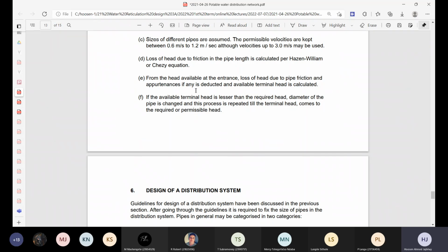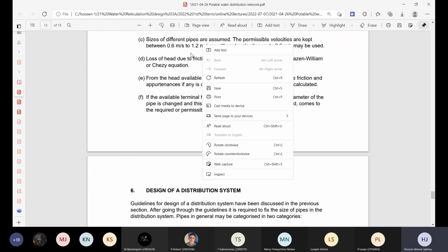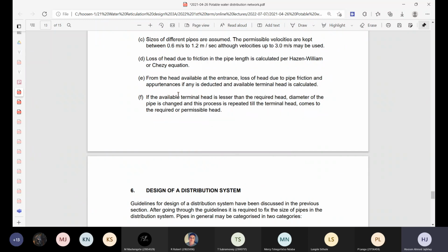Or you might even go into negative pressure, which means the pipe size is totally inadequate for your system. If you get hardly any friction loss, then from a point of view of economy, you might try a smaller pipe size. Yes, you'll get some larger friction losses, but maybe you're still within the 24 to 90 meters of head, and you might find that an acceptable level.